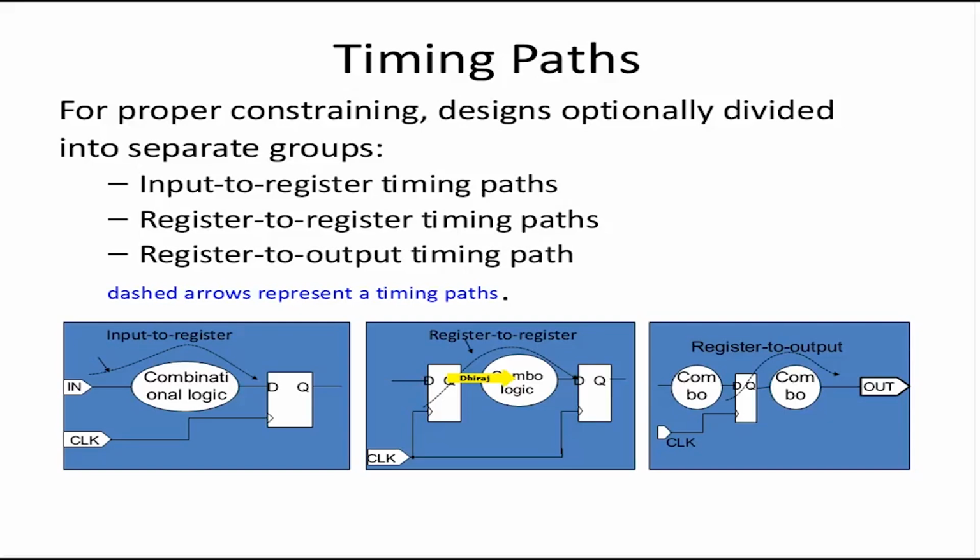DC will still do the synthesis. It will still do synthesis even if it does not know what your goals are. It will by default optimize for lowest area. So the resultant design will be very slow, but it will be area efficient. But since there are no goals in place, it's irrelevant. What I'm trying to say is that DC knows the cell delays from the library. It will know the net delays, that is, the estimated values from the wire load model.